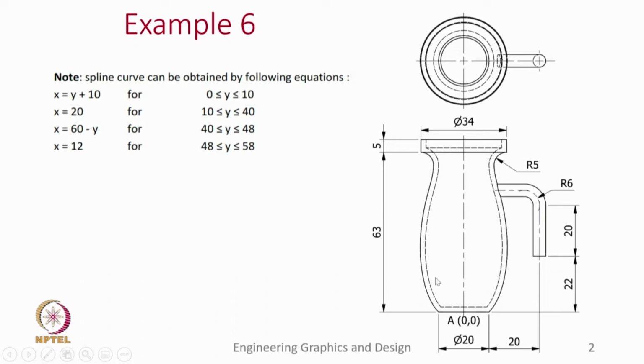So, let us look into the front view and the top view and try to understand what tools we may need to use to create this solid. These dashed lines indicate that the interior is hollow, which means we will be using the shell tool.